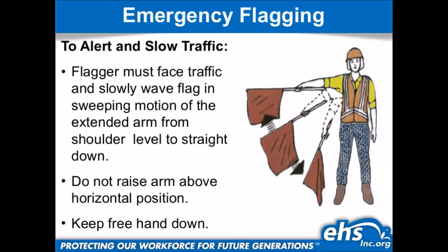For this one, your free hand drops down, and this is the only time you're going to be waving the flag up and down. If you've ever seen people try to emergency flag, sometimes you see them waving cars by like a NASCAR. That's not how it's supposed to be used. The only waving is up and down, and that's to tell people, hey, watch out, there's a hazard ahead. Slow down. That's it.